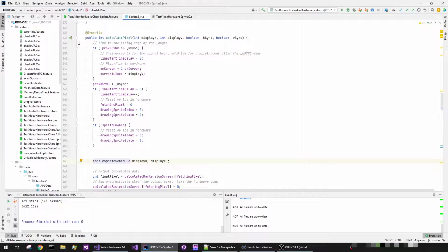But having it 512 bytes wide meant that I didn't have to invest too much time in horizontally clipping or rejecting the sprite data as I was calculating into the Sprite Scanline RAMs.